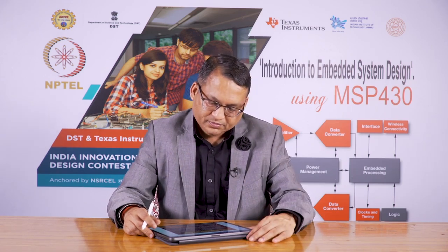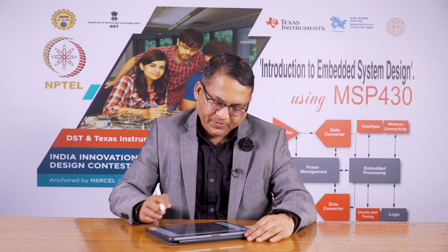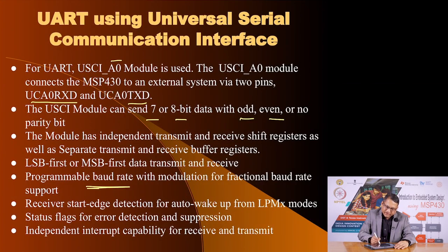So, essentially the UART interface acts like a serial register, meaning it works parallel in, serial out for the transmitter, and for the receiver it is like serial in, parallel out. You can decide whether you want to send the LSB first or MSB first. The standard method is to send the least significant bit first. You have programmable baud rate, which means you can change the bit rate for given clock signals available on your microcontroller, to support any of these standard bit rates.